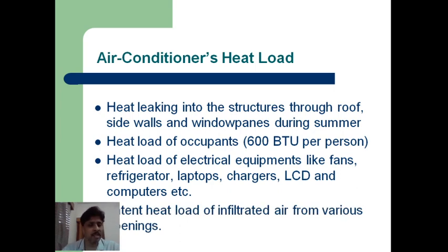The last one is the latent heat of infiltrated air. Now what is infiltrated air? This is air which leaks inside the space through various openings, like the sides of the windows, the sides or bottom of the doors, cracks in the walls, and ventilators. This air may be moist, and if moist air comes inside the refrigerated space, a lot of additional heat load is added. So these are the main heat load factors which we should consider before calculating the heat load of any space.